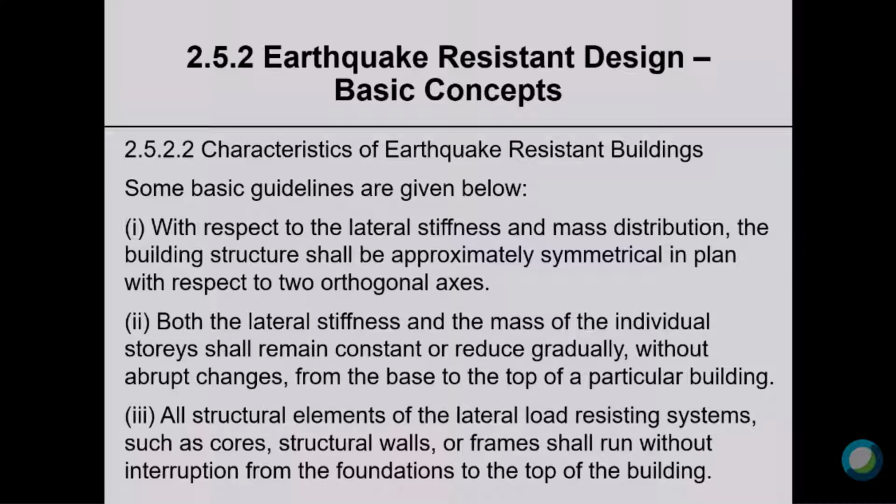So all structural elements of the lateral force resisting system shall run without interruption from the foundation to the top of the building. Typically, it is not something that you will encounter.